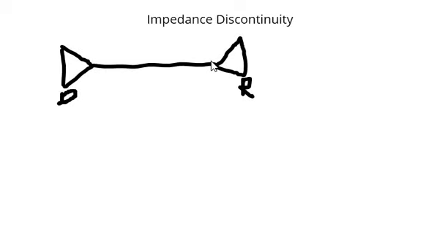This is a signal path between the driver and the receiver, basically a routing between the driver and receiver on a PCB, right? So whenever a source sends a signal to the receiver, basically the zeros and ones, if this signal sees different impedances along its path between the driver and the receiver, then such a condition is impedance discontinuity, where the signal might have reflections because of this discontinuity and it gets distorted.